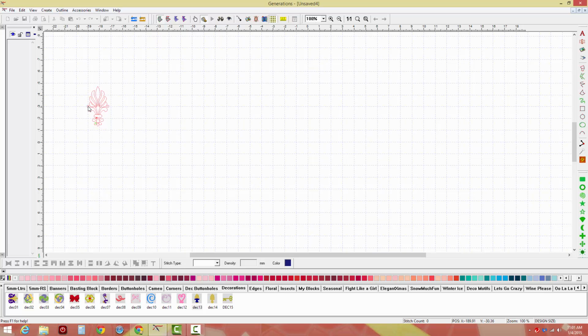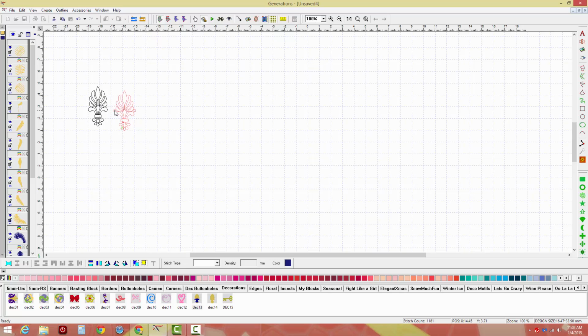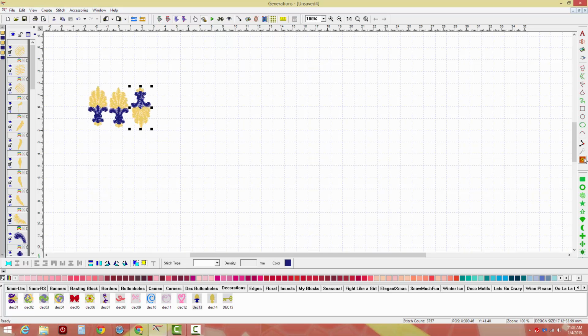To use this feature, I place a left click to anchor the design or the wireframe design, and from there I can either place a left click here and just create the item, or I could place a left click and I can rotate the item, or I can place a left click and I can right click to flip it and still rotate the item. That's a continuous input option, and it does show up in wireframe until I generate.